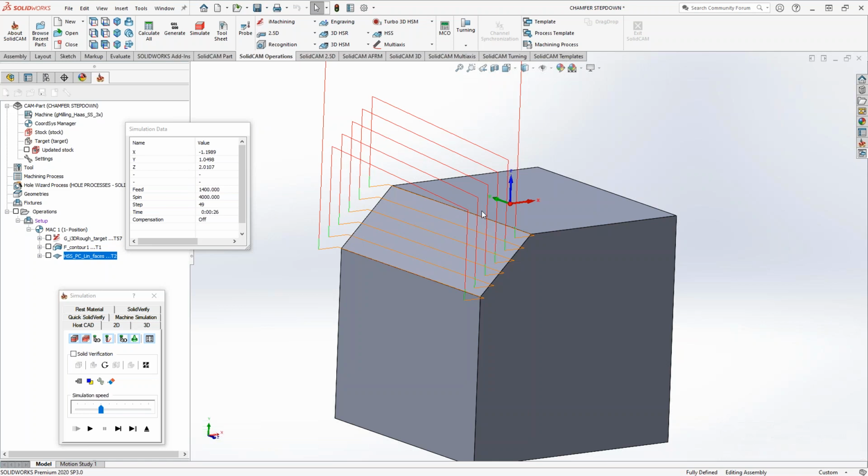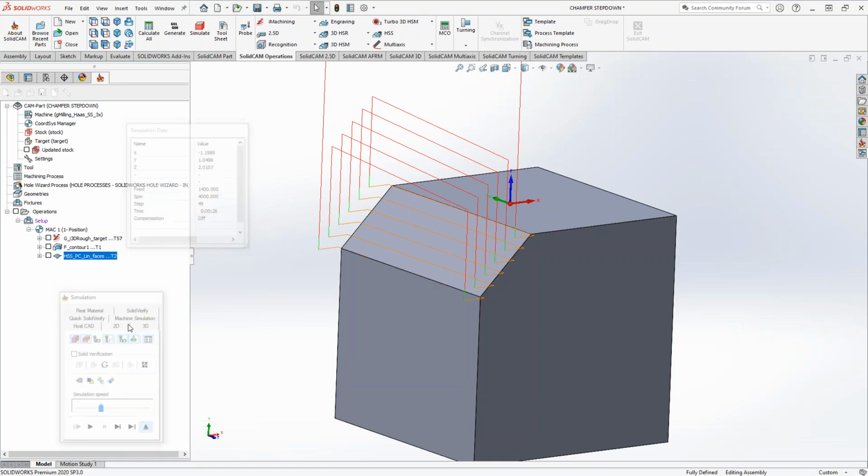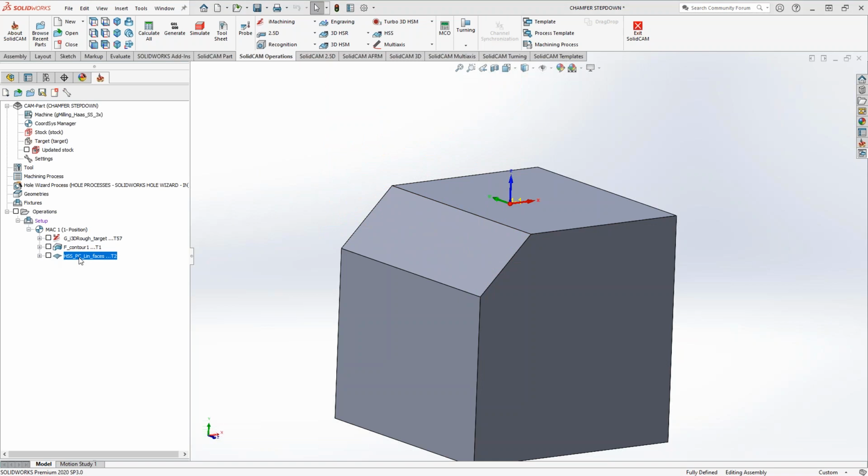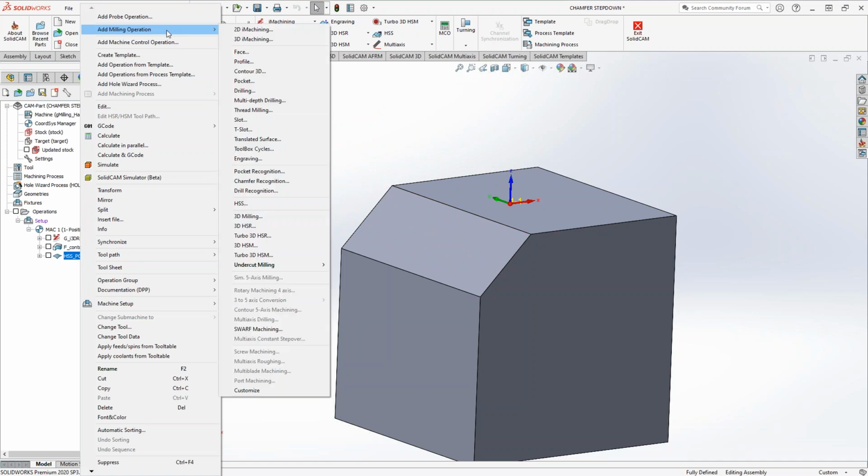Whatever it is, whatever tool you have, there's a way to do this with HSS. Or if you got the chamfer mill, you can use these two options here. And maybe any questions on that? Let's show them. If we didn't have a chamfer mill, if we didn't have a spot drill, if we didn't have any tool with any kind of chamfer, let's show them a toolpath using a ball mill to get that same result, as well as maybe a bull nose.